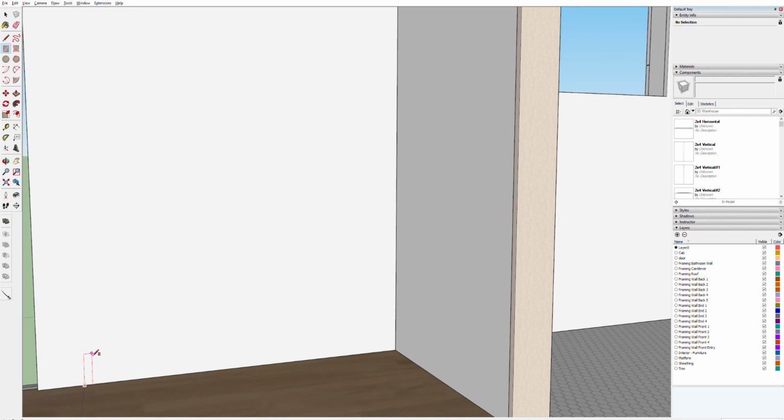Okay, Mr. Rectangle tool, going up 11 3/4, comma 0.75. So there's that. And now the tread width was 9, so we're going to add on that 3/4 of an inch for this scenario. So that'll be 9.75, comma 0.75. Let's add this guy right here.